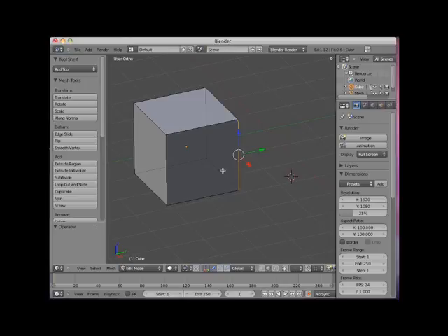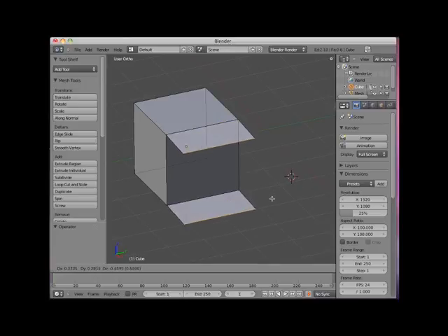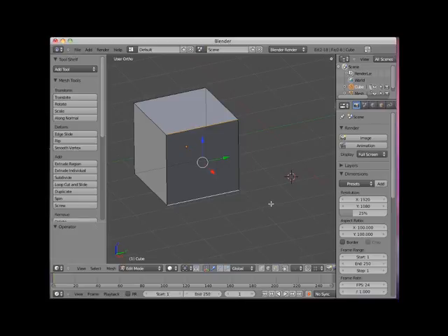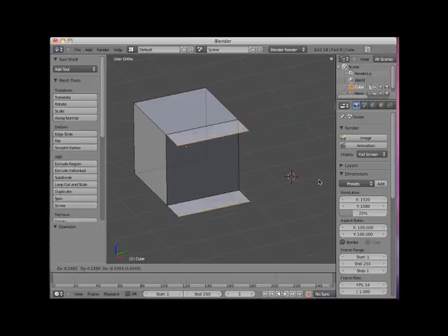I will select the top and bottom edge, and then press the E key, Extrude. Note that the extrusion is placed in grab mode, and I can move the extruded edges anywhere and left-click to place them. I'll escape this extrusion. With the two edges selected, I'll press the Extrude Individual button. Note in this case that there is no difference between the Extrude Individual and Extrude Region.